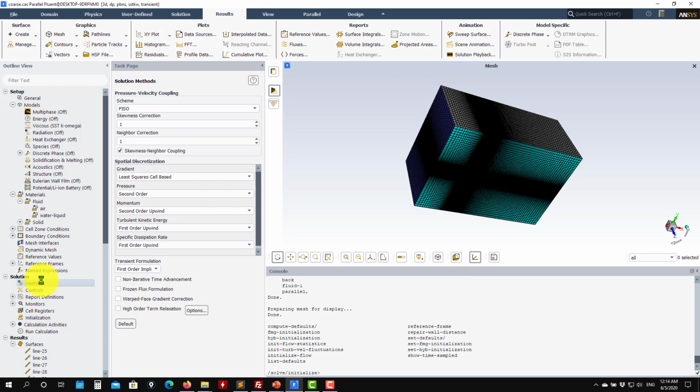Here we have access to the transient solver. By default, Fluent now is not proposing the coupled solver. You do have the coupled option, but I want to remind you that the coupled solver is very computationally expensive. It's worth using if you're working with a steady solution. For unsteady solutions, it's not recommended, it will slow down the computation. If you want, you can do your benchmarking, but you will realize that. So stay within this family of segregated solvers.